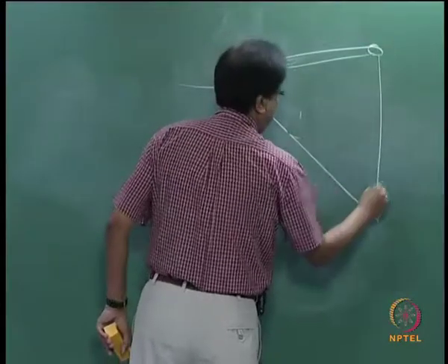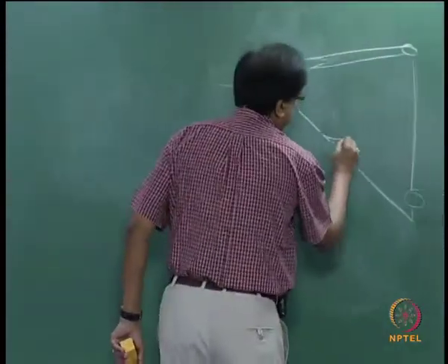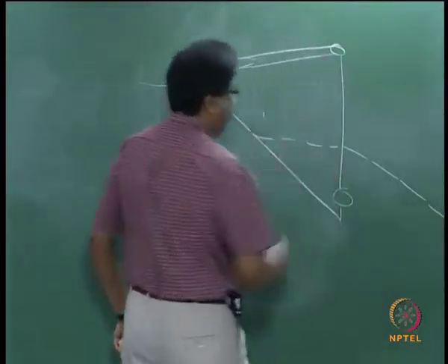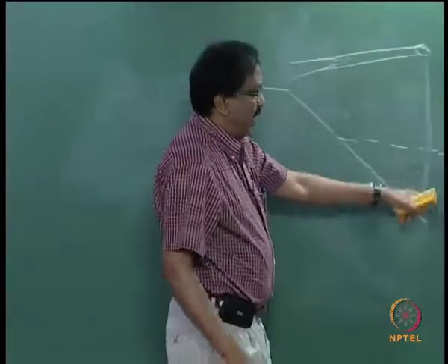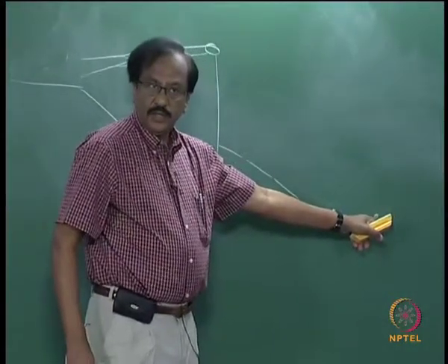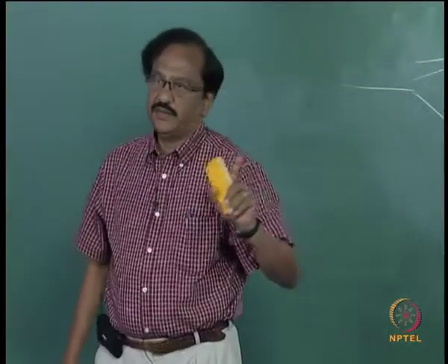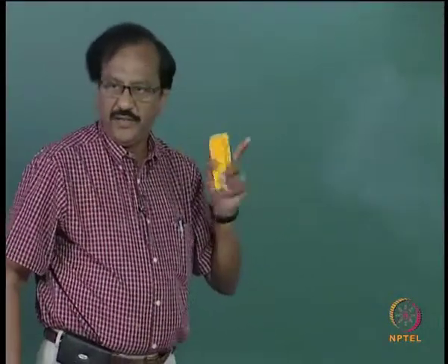So, you can place the stones, but if you have a berm, then what happens? The boom length has to be more. So, it calls for a special kind of crane. So, these are all site specific.